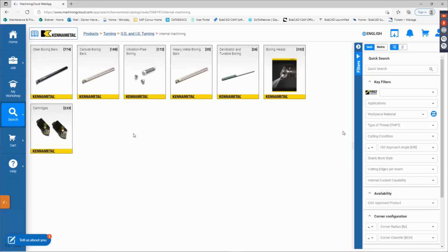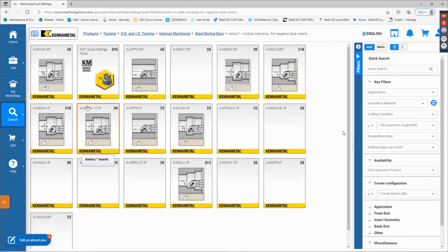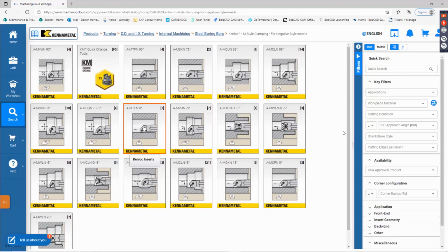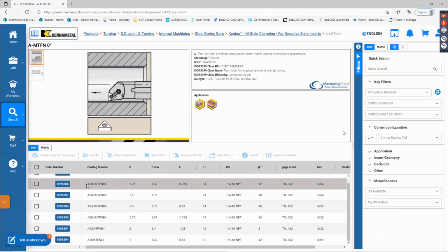Because this is one of the biggest things with our software. Anything below 33 there, we don't have a way to really set up for a boring bar. So if you can download one, I'm just picking one off the top of my head here. You've got different options in here. Let's go with this one. This one's got 7 different types in here.